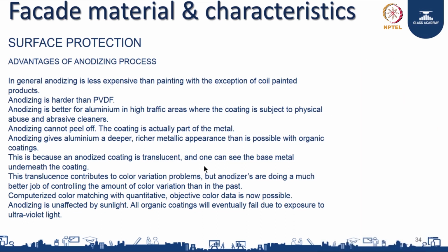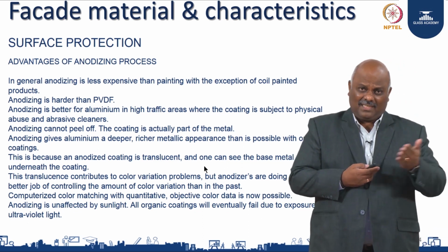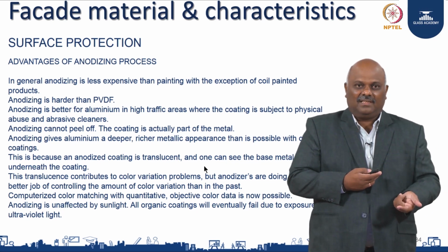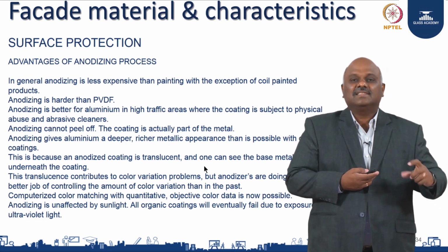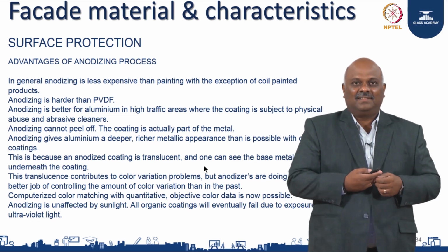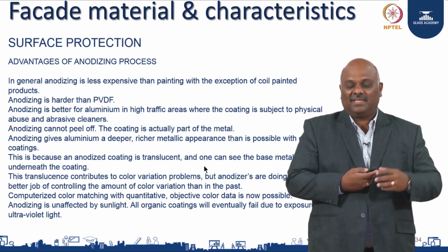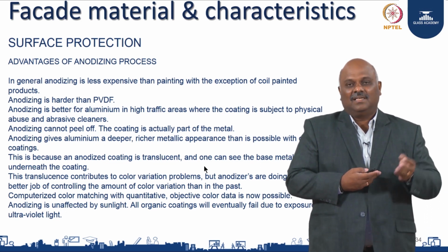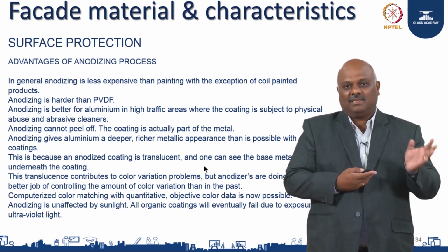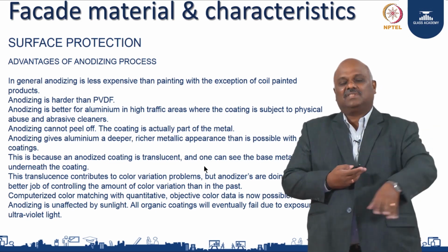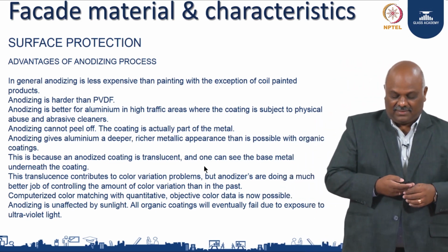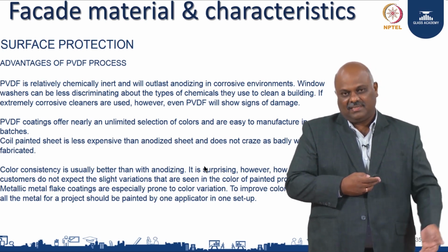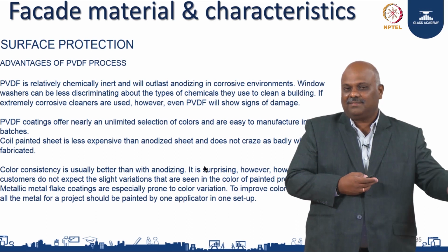So, there are a lot of different varieties of systems available, but there are three common ones, which are anodizing, powder coating, and PVDF. Anodizing is changing the material hardness by improving the surface in the form of an anodic process. Powder and PVDF are deposits. It means something you deposit on top of the mullion, like paint. PVDF and its advantages, as I said, it can be fixed easily. If there are scratches, dents, whatever, you can repair.